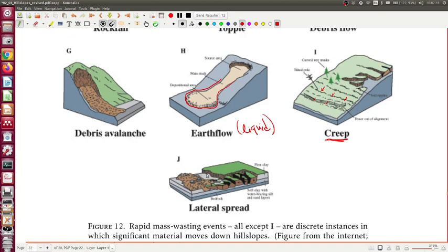So let's see, if we have something like a river valley here, then this is creating a free surface. In that case, if there's something in the middle here, this block is supporting this block over here, but over here, unless you're actually here pushing on it as a person, there is nothing holding this side up, so material can spread out to this side laterally.